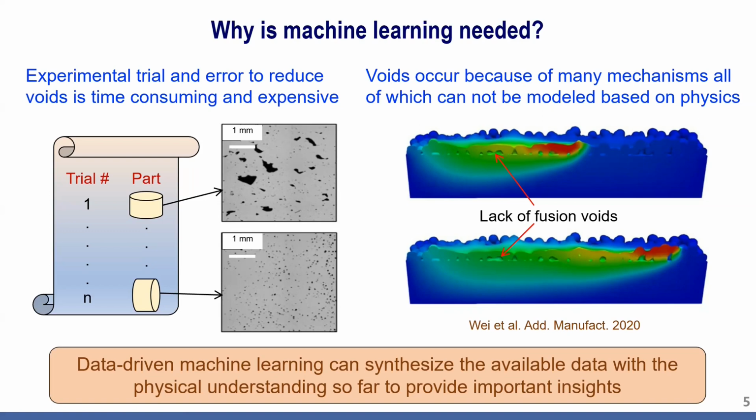The voids can also be understood from much higher resolution models that we call powder scale models. These models typically do a millimeter or 2 of simulation and take an enormously long time, but can resolve the lack of fusion voids. They are very expensive, very time consuming, and they have not been standardized for avoiding these defects.